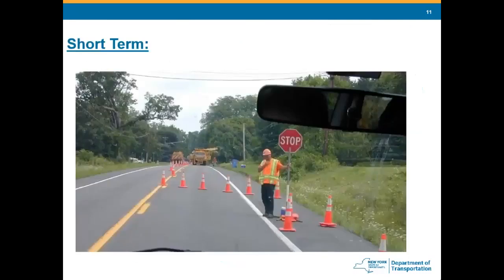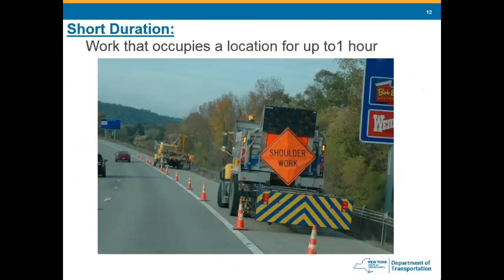Short term. Short term is also stationary. Daytime work occupies the location for more than an hour. So something like guide rail repair, something along that line. And short duration is going to be work that occupies a location for up to an hour. Again, daytime work.